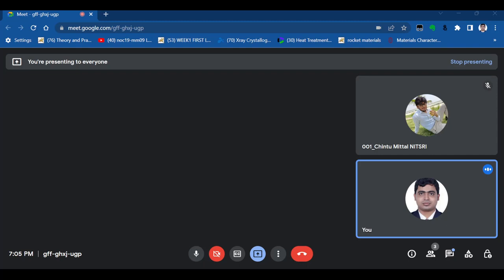So then we will check the options here. The same weight fraction of liquid and solid, but the solid composition, this is not correct. Same composition of liquid, but the weight fractions of liquid are different. This is fine. Same weight fraction of liquid, this is not correct. Different compositions and weight percent, composition is not different, same composition. So this one is the right answer, B. Same composition of the liquid, but the weight fractions of liquid are different.